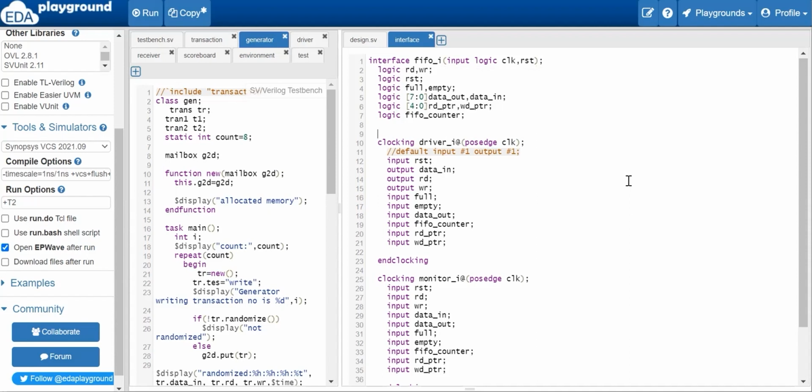That's why logic is a new data type created in SystemVerilog. By using logic we can write either reg or wire, with no need to mention reg or wire particularly. In place of both we put logic, to avoid the confusion.